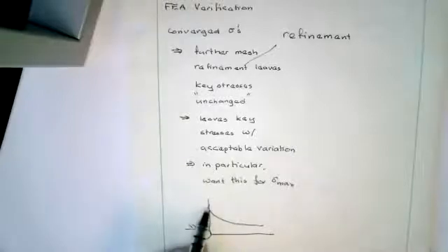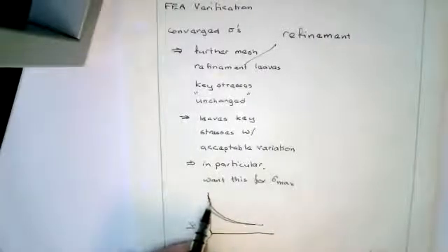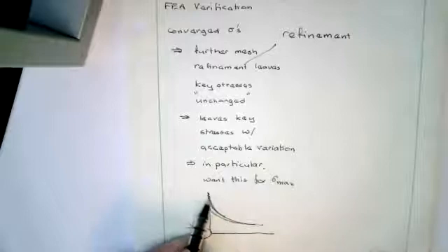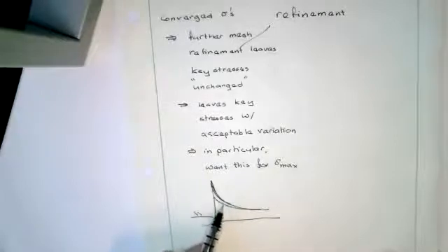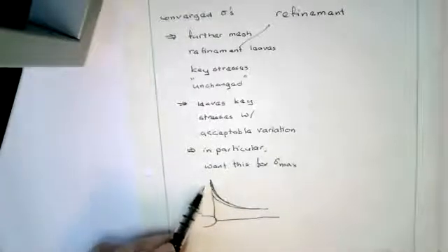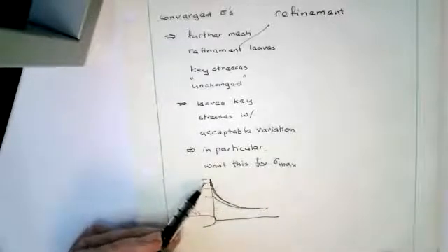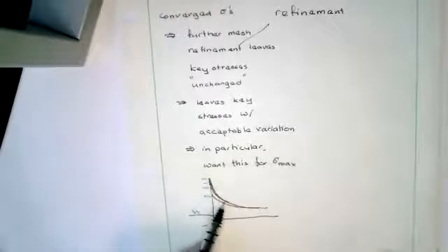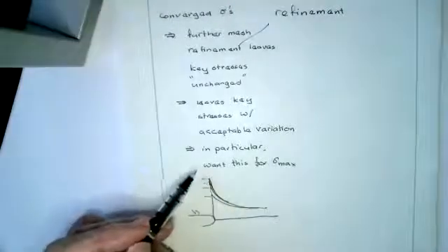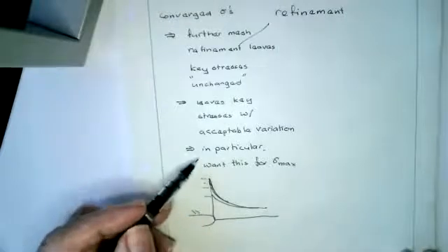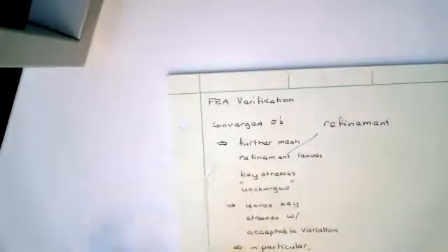And as you refine the mesh, away from the stress concentrator it starts to converge, but here it's still changing a little bit. My figure's not that clear, but these values are still increasing. They're increasing by reducing amounts, which is encouraging, but they're still changing. Whereas when you get away from it, you pretty quickly get convergence. So you're going to want to get this to happen for sigma max. So we have to decide how we're going to refine our mesh.